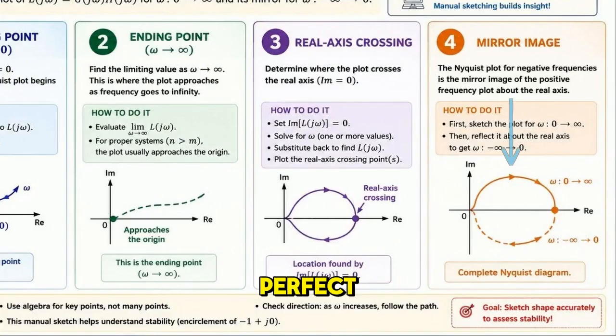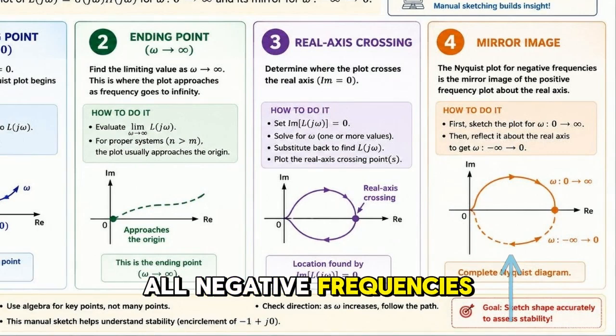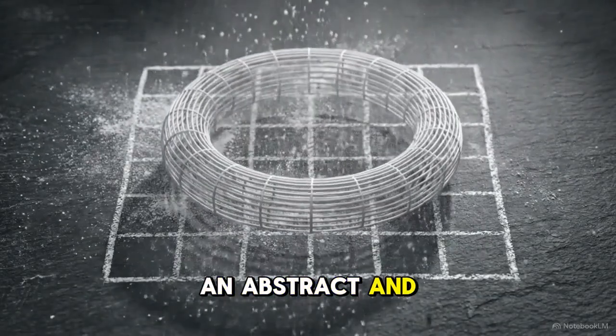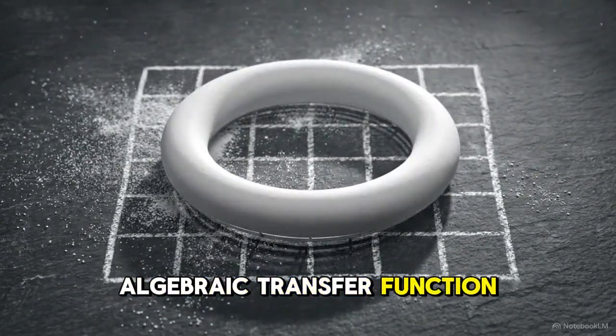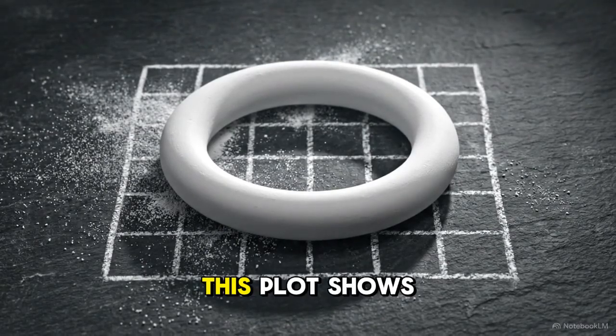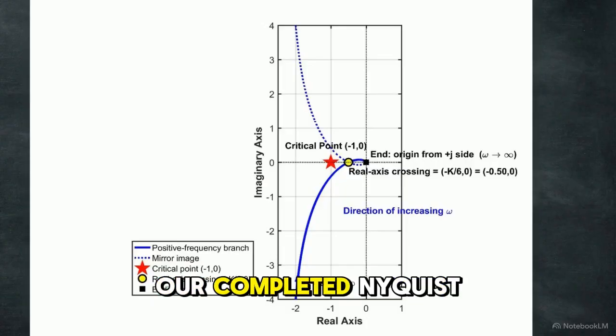Step 4 completes the geometry. We draw a perfect mirror image of our positive frequency path, reflecting it across the real axis to account for all negative frequencies. Through these 4 boundary tests, an abstract and intimidating algebraic transfer function is successfully trapped as a tangible geometric shape. This plot shows our completed Nyquist contour.